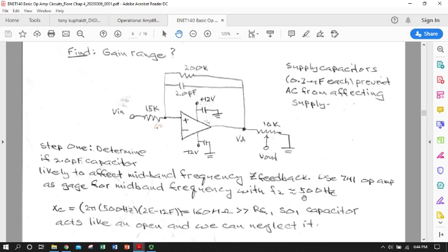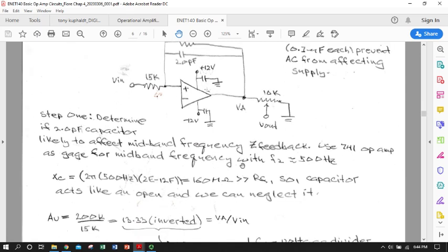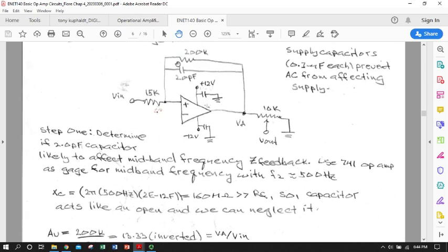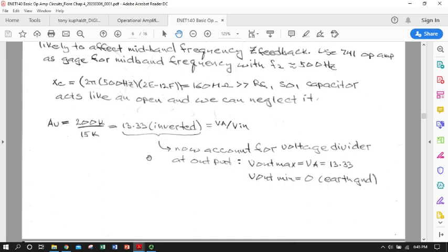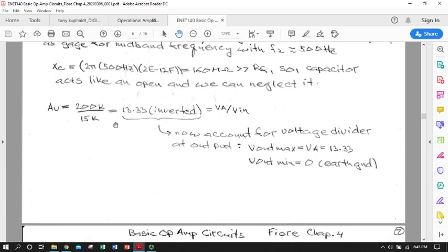And again, that's very likely because our upper critical for this particular op amp isn't a very, very high frequency. Had it been higher, that may have been different. So again, that'll depend on where your midband is in an absolute frequency standpoint versus the capacitive reactance here. So that's a good example of being able to design a circuit for frequency dependence and tune it by just simply using our formula. But we would of course have to use it correctly, the -1. This would have been correct had it been an inductor, and that had been in Henrys. Probably wouldn't have been using a big inductor with an op amp though.